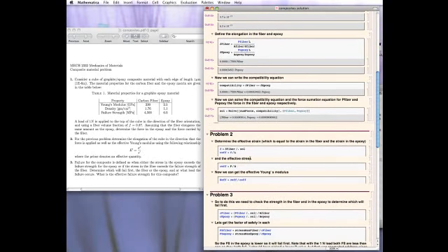All right, so the second problem is to determine the effective Young's modulus. Every time we talk about effective, as we mentioned in class, this refers to the Young's modulus of this composite system consisting of the fiber and the epoxy. If I consider it to be a homogeneous material, that's what you would get. To do that, we're going to use the relationship that it's the effective stress over the effective strain. So we need to define both of those.